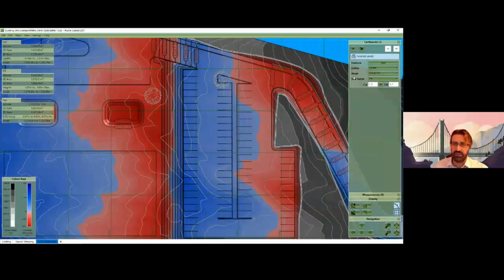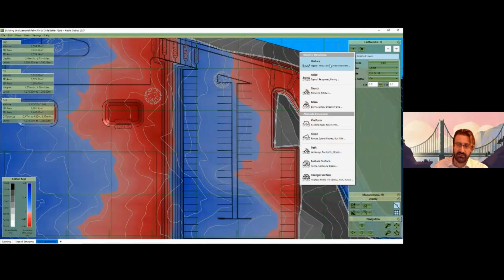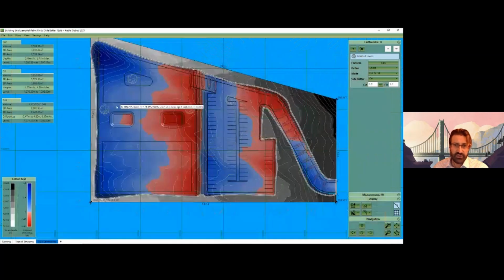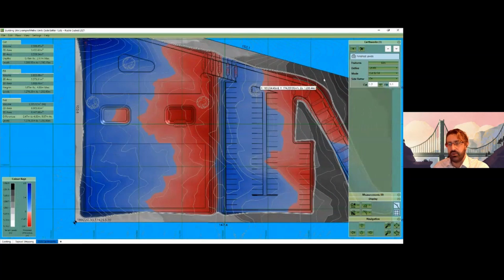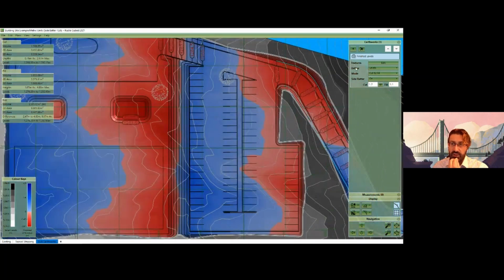But there was another method, which was to add strips, now renamed to reduce elements, over the top and reduce the element that way. That used to suffer from the same problem as the strip, that if they intersected, it would then reduce cumulatively, which we don't want. So now the new system sets it to adjust from the finished levels here. And so if they intersect, because the depths are from the finished levels, where they intersect, one will take precedence.